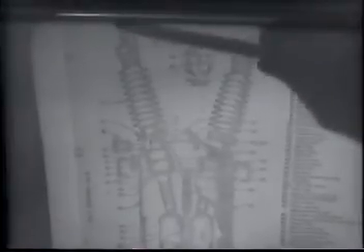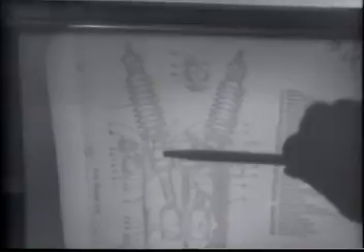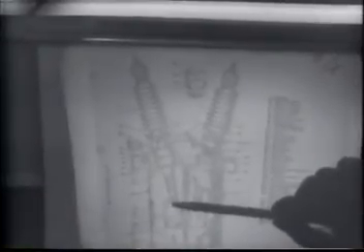But to continue, the current path would be through the bushing, through these devices here that are called current transformers, and we'll talk about them later, to the bottom of the bushing. At this point, we have the circuit interrupter molded to the bottom of the bushing. This is the device that we'd mentioned in the two earlier transparencies that interrupts the arc. And then coming out of the bottom of that is the moving contact.